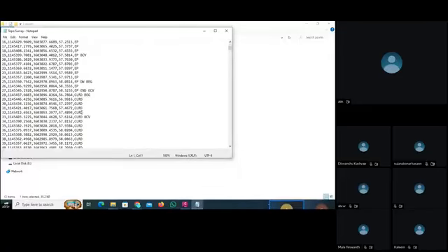Then for the vegetation, it is denoted as ESHB. For fence, it is FNC. For ground shots, it is ZS. For break lines, again, it's SWL. For vegetation, TR is also included. For break lines, they mostly use SWL, TOB, and TOPD. See here, you can see BOTD. It is also for the break lines.